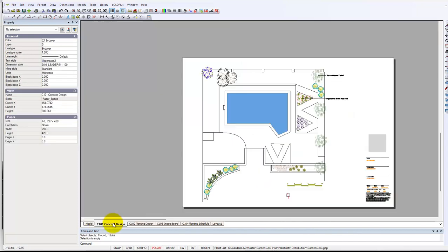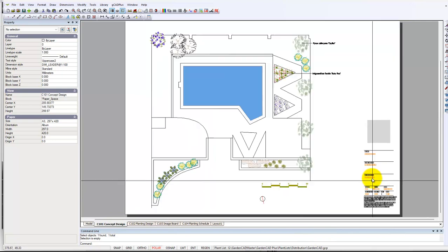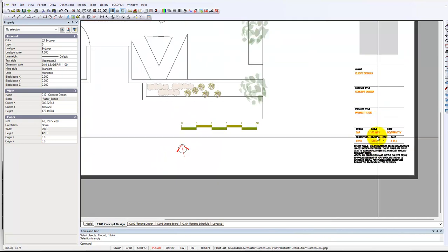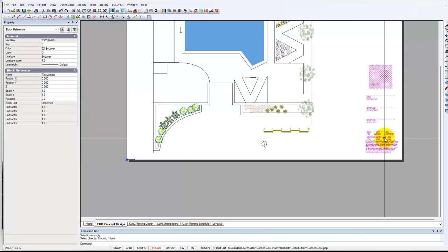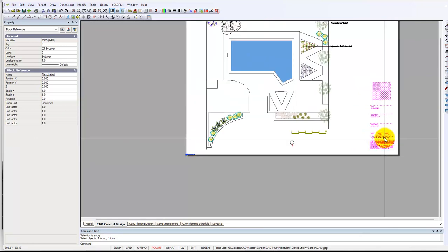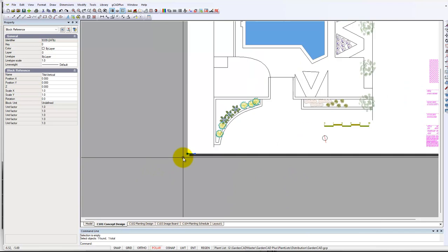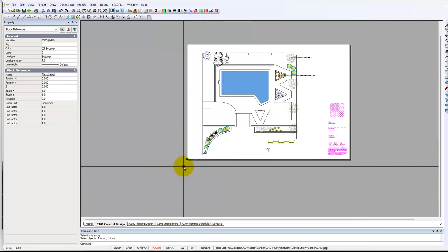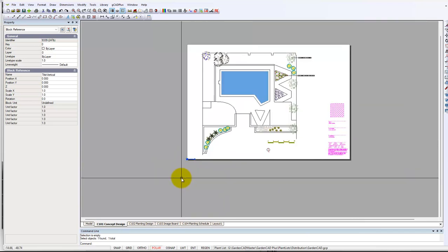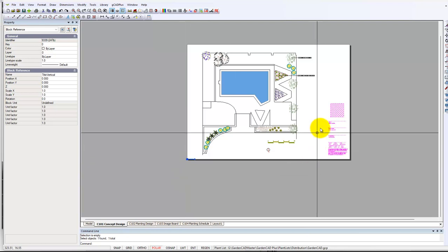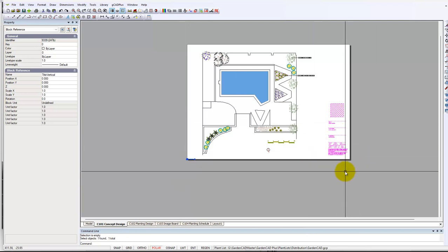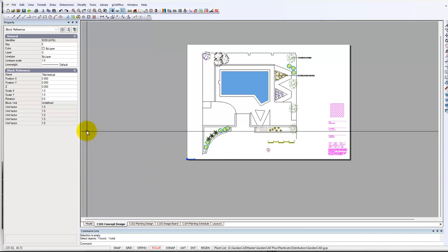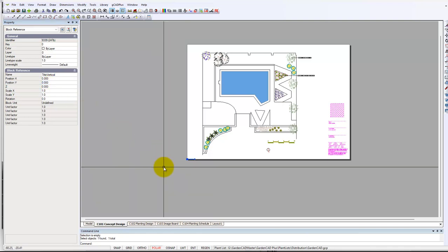If we come over here, the vertical drawing title block, where we put information on the client name, scales, and so on, has a base point anchored down here. The reason for that is that when we insert our title blocks, we simply put them in at an X position of 0 and a Y position of 0, and then the block will orient itself nicely on the sheet.